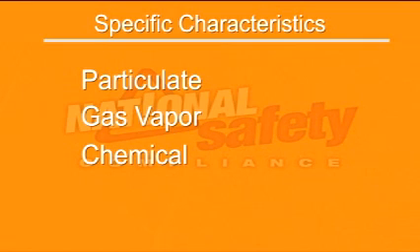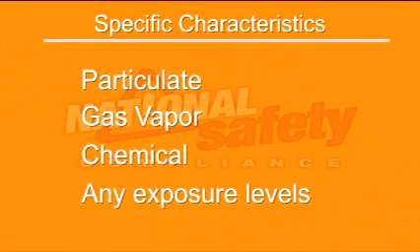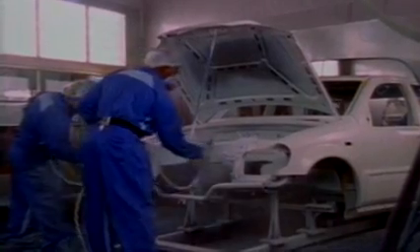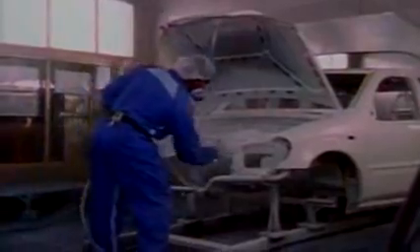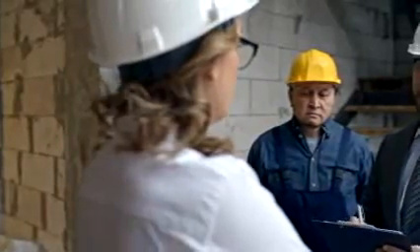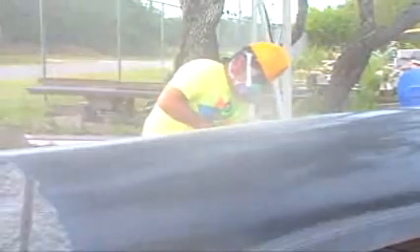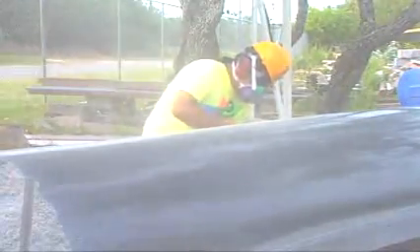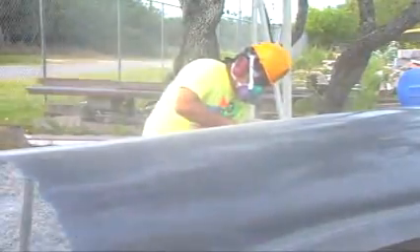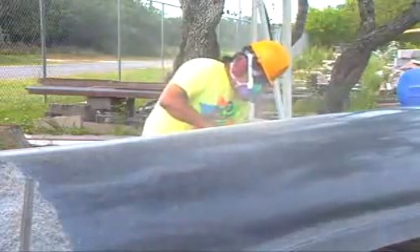And if so, are there safety data sheets available? Are there any mandatory or recommended occupational exposure levels for the contaminant? These questions must all be answered to ensure employee safety when selecting and using respirators. When employees notice symptoms or complain of respiratory health effects, or if the workplace contains visible emissions such as fumes, dust, or aerosols, an assessment should be performed.